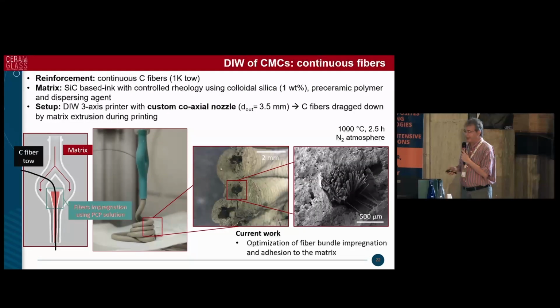So we have developed a new approach just very recently, where we have a coaxial nozzle, and we are extruding the parts. In this way, it's very easy and it works well. We will still have the issue of cracking after pyrolysis. This is a pyrolyzed part. There are not many cracks, but this is due to the fact that we still have to improve the adhesion or the interface between the fibers and the filaments.